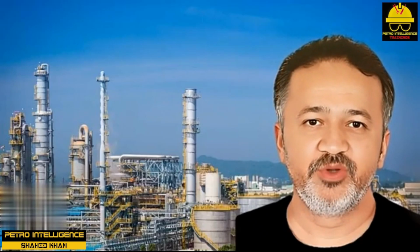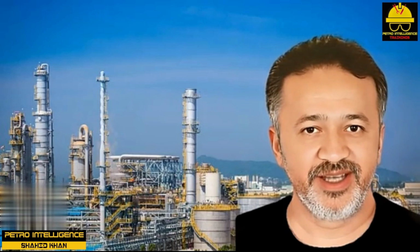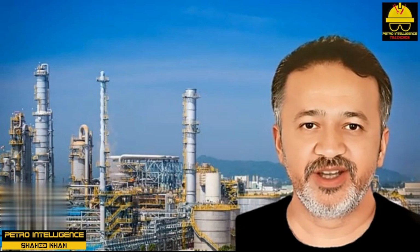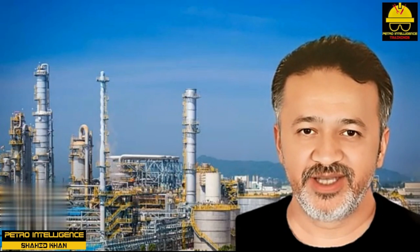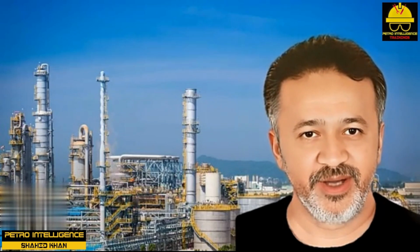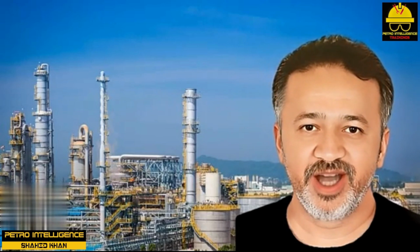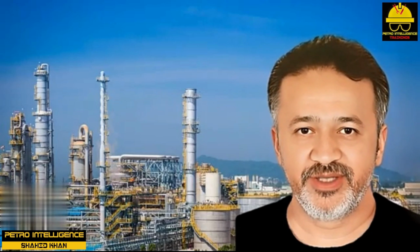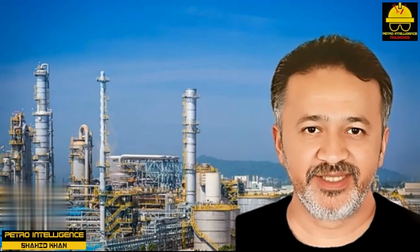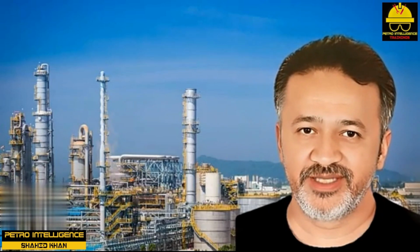New high-capacity trays. All vendors now market a high-capacity tray. These trays have a 5 to 15% capacity advantage over conventional trays. Basically, the idea behind these high-capacity trays is the same. The area underneath the downcomer is converted to bubble area. This increase in area devoted to vapor flow reduces the percent of jet flood.